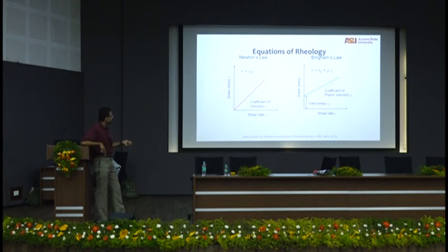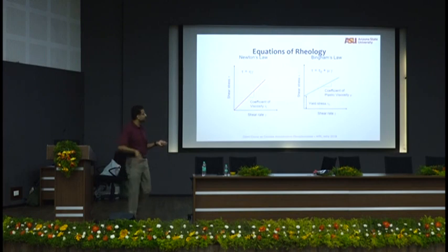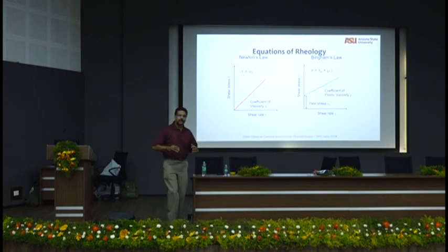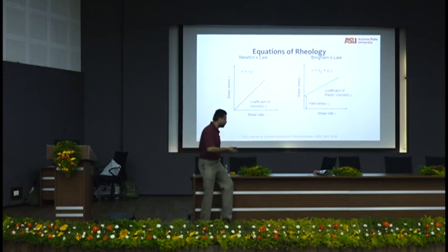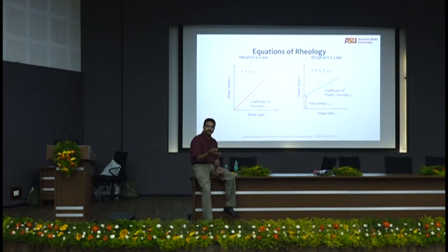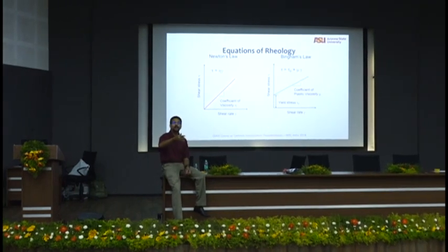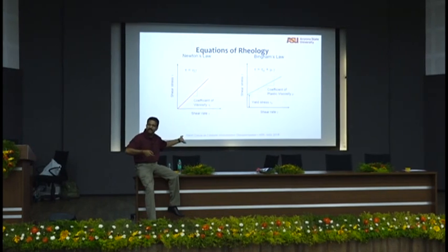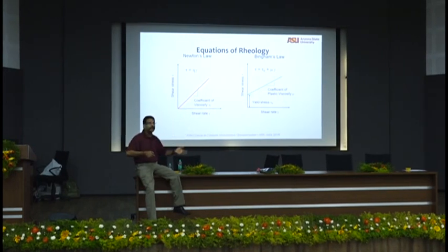Concrete, cement, paste are all what we call Bingham fluids. It's not strictly a Bingham fluid either, but for the time being, we'll assume it to be a Bingham fluid, where you need to give it some energy, some critical energy, beyond which it will start to flow. So you have to get it to some shear stress beyond which it will start to flow. You can relate it back to the concept of activation energy I gave you earlier. You have to give it some energy to overcome a barrier. It's the same barrier it's trying to overcome. You see that? The same idea I gave you yesterday. It's overcoming the same activation energy barrier. You give energy, give energy, give energy.